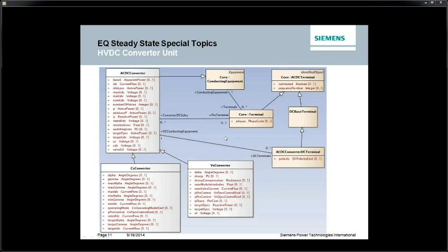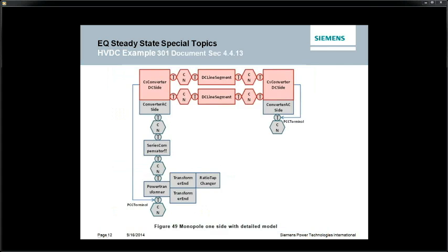In addition, as I said earlier, you're able to encapsulate certain AC equipment and associate it with the actual DC model, so that you can actually model a transformer and, like I say, series devices or any tuning compensators. And you set a pointer or association from the AC-DC converter out to the terminal that's furthest away from the DC equipment to encapsulate all that. The next slide actually shows this.